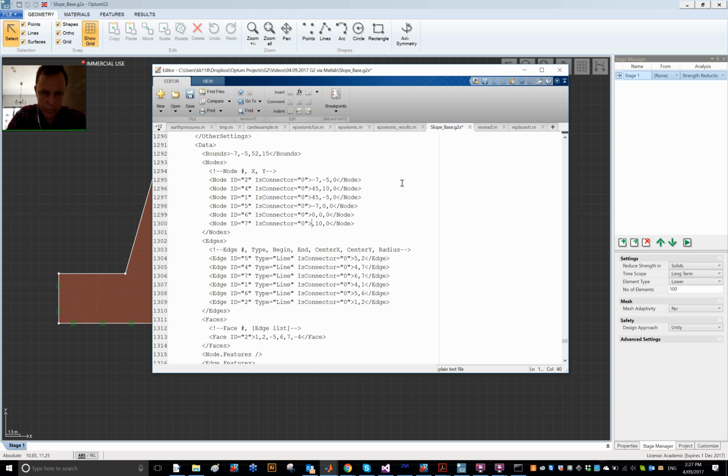Instead, I'm going to set things up to have this change done in an automated manner. I'm going to define a variable, and I'm just going to call it x. I'm going to enclose it in dollar signs. That's totally optional, my own personal preference. I know there are no other dollar signs in the input file, so whatever I enclose in dollar signs is going to be a unique string.